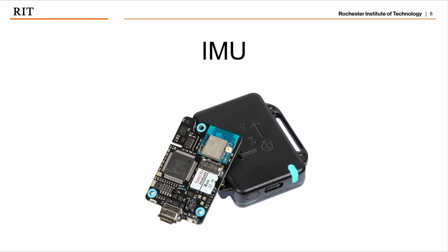For our probe, we needed a way to track 3D position. The most cost-effective solution we came up with was an IMU. The XIO IMU3 met our needs for cost-effectiveness, and we believed we could use it to do position tracking. Since the IMU tracks acceleration, we needed to do a double integration to get the position of the IMU. Problems arose with the noise, as it is exacerbated with double integration, leading to significant drift issues.